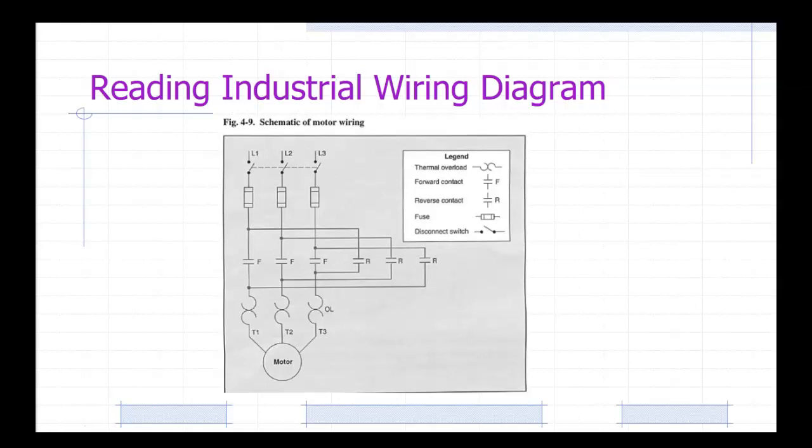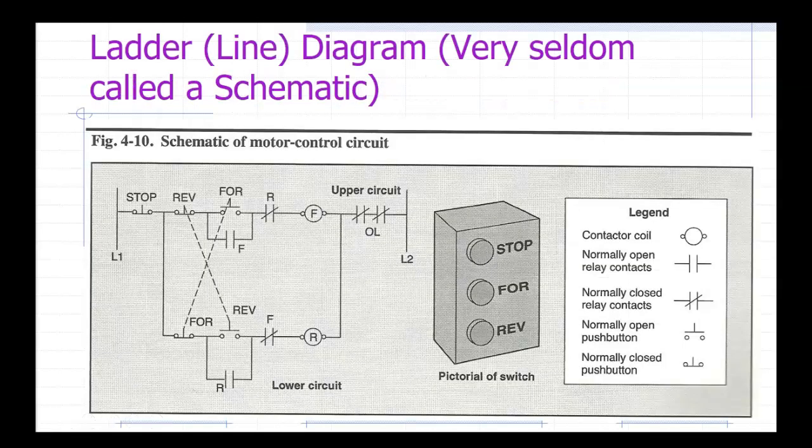If the fuses don't work, you have these thermal overloads. So if the motor starts overheating too much, if it's drawing too much heat, these guys open so that your circuit will break. Why? Because motors are made of copper wire and they're expensive. Not to mention they are really hard to replace sometimes. Those things are heavy. Okay.